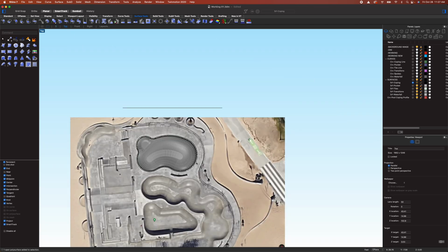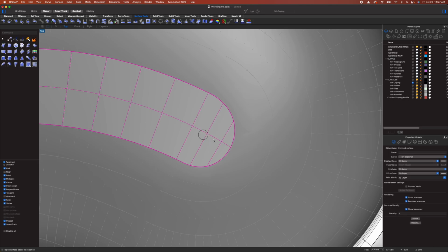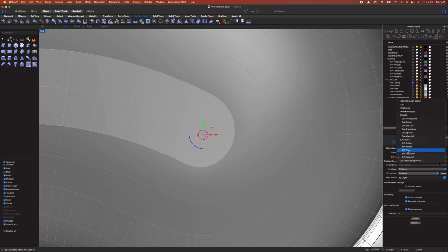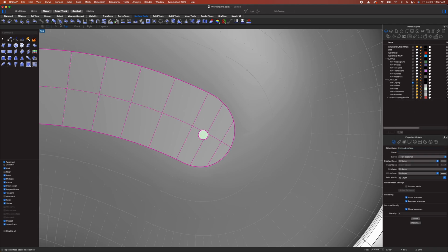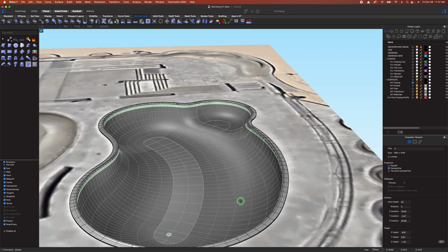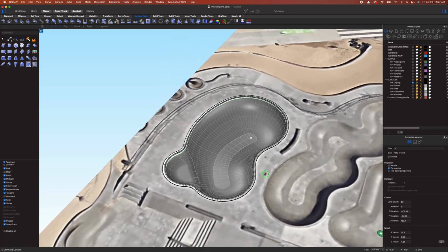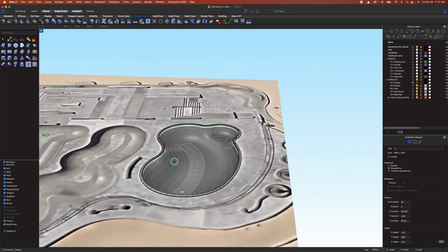Let's just add a drain plate now. We'll draw a circle in the center here. Let's go diameter 9-inch. And then the same thing, we're going to select this object and split it with this circle. And let's just put this on the tile end so we can see it as a different color. Get rid of that circle. And there you go. That's a pretty nice model right there.